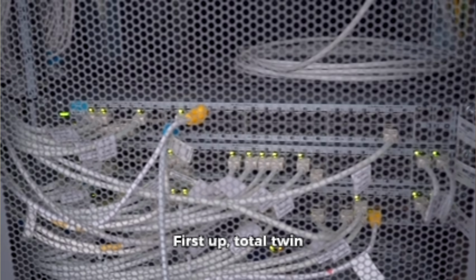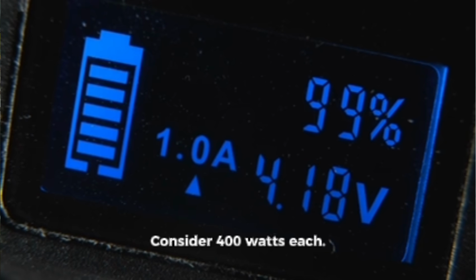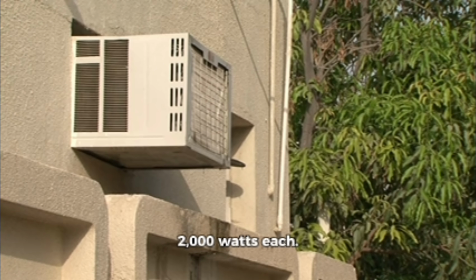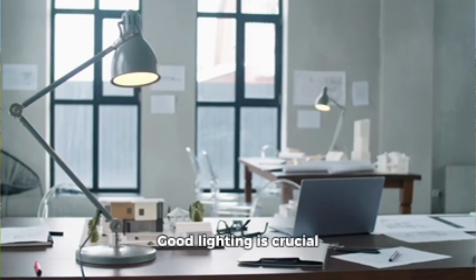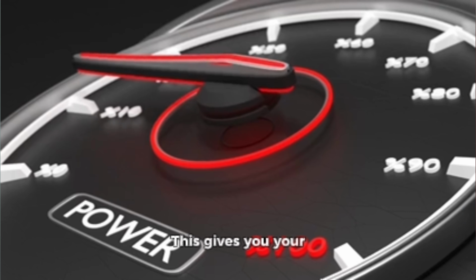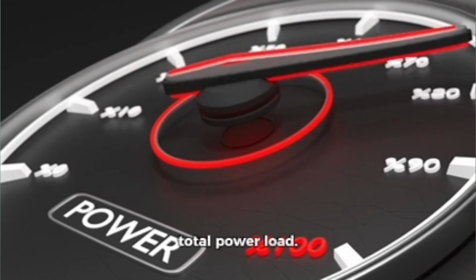First up, total twin sockets in the floor is 100 nodes. Consider 400 watts each. Consider 6 AC units, 2,000 watts each. Finally, consider the total light load, approx 5,000 watts. Good lighting is crucial for productivity. Add up all these power requirements. This gives you your total power load.